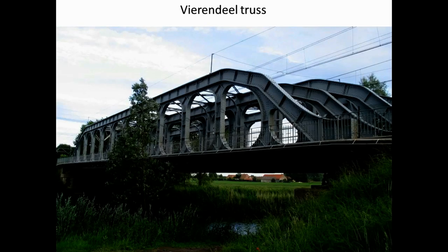Now if you go back and recall some of the trusses we looked at earlier on, instead of having big triangles here bracing it, there are just little triangular edges for each of the uprights, and that's doing the job of bracing the overall structure. And this has got a name because it was invented by Mr. Vierendeel, and so they're known as Vierendeel trusses. And if you're designing what we will look at at some later stage, what we call a habitable truss, in other words, if that was a building that was spanning and these were glass openings, let's say, and you didn't want big triangles in front of the glass, this would be how you would solve it with the Vierendeel. Okay.